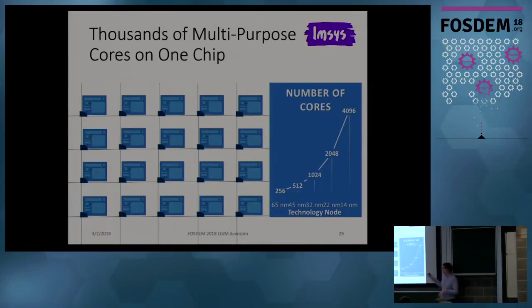In this case, each processor core has its own microprogram, and it's software configurable. So depending on the application, the software itself would be able to dynamically reconfigure and repurpose each one of the cores separately, depending on the actual application requirements.